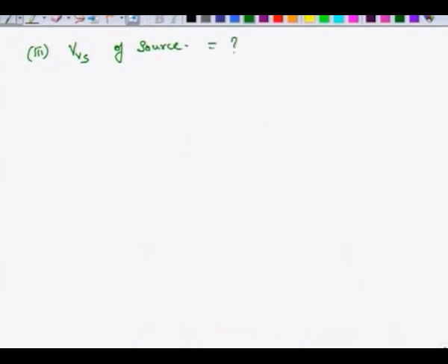So, what is the volume velocity of this source? We have seen earlier that the relationship between complex pressure P(r, omega) and volume velocity is this. P(r, omega) is equal to j times omega times density divided by 4 pi r, times e to the power of minus j omega r over C, times V_S.